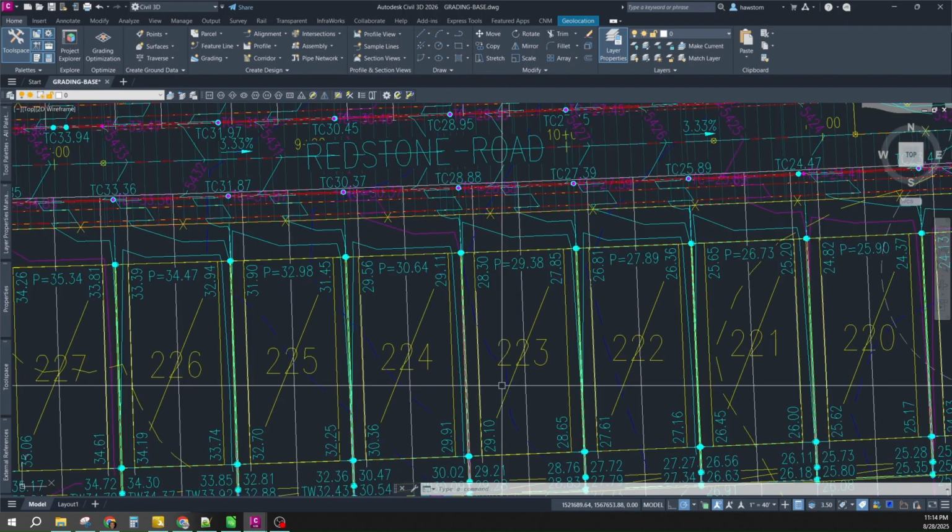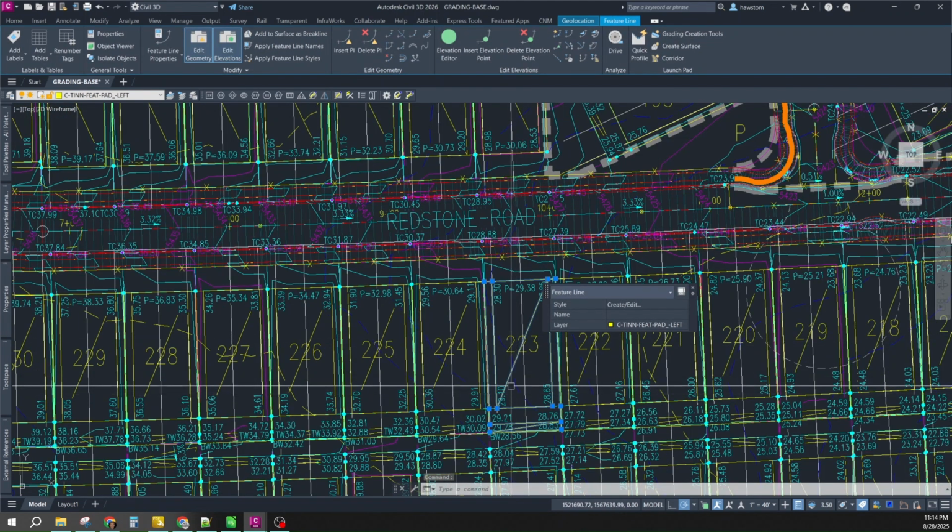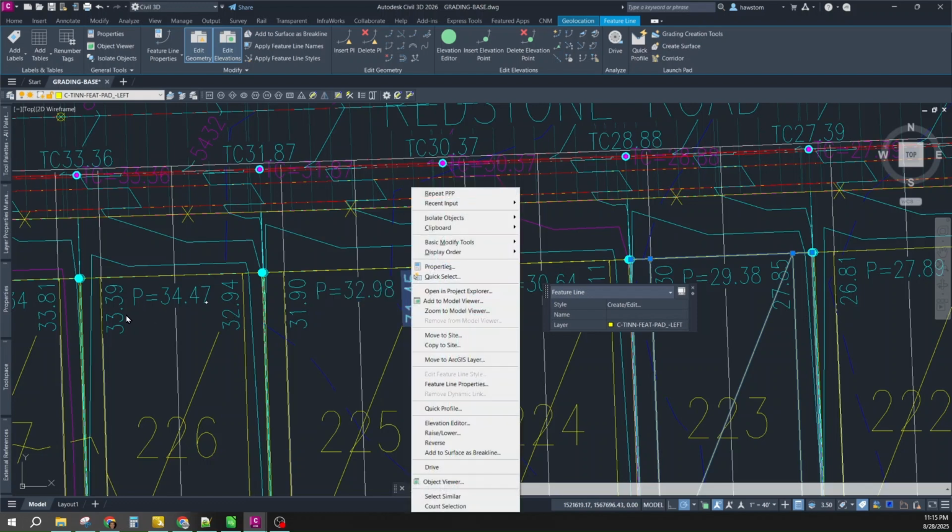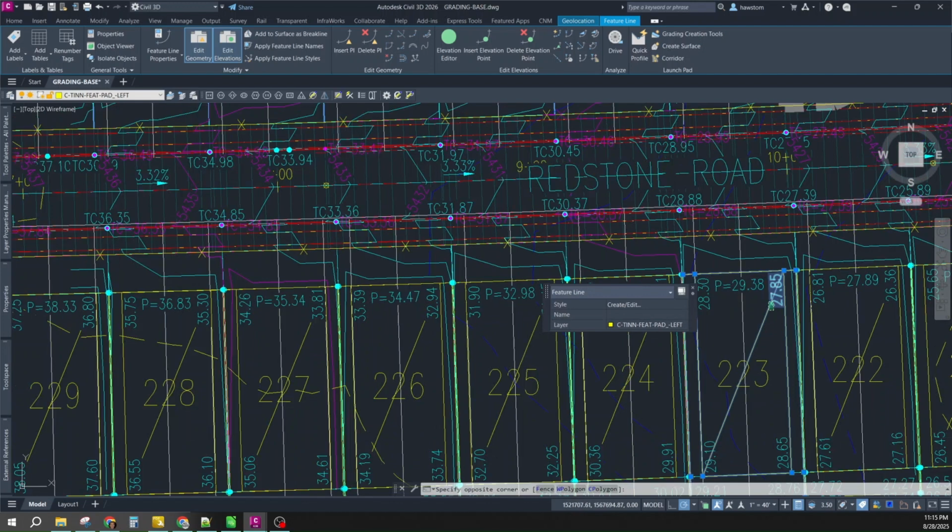The second thing is that we have on each lot a standard pad grading feature line that includes labels and fixed grading. We do not change this grading for any lot. If you go and look, every single lot is 0.55 from the low side to the high side. 94, 39, 85, 30.